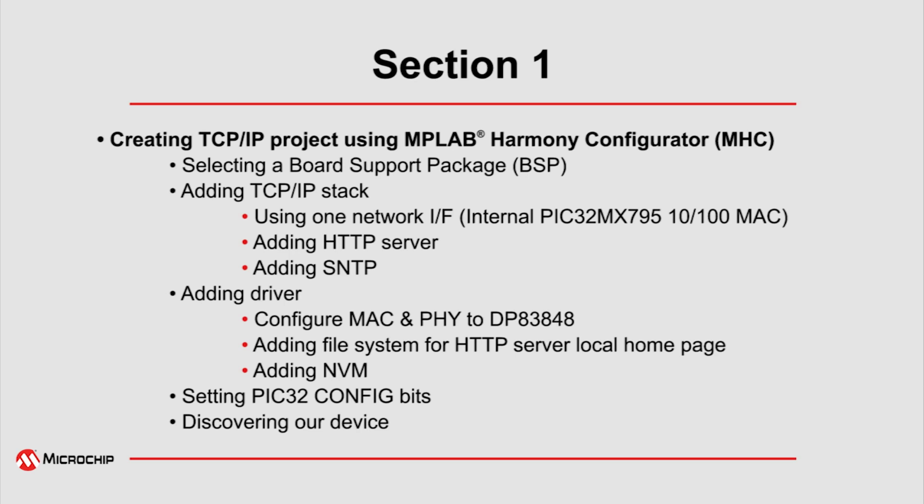We will add Simple Network Time Protocol to allow the SSL library to validate the issue date and expiration date of the certificate provided during the SSL connection. We'll be adding drivers to configure the MAC and the PHY attached to the PIC32MX. We'll be adding the file system for the HTTP server to retrieve the local web page.